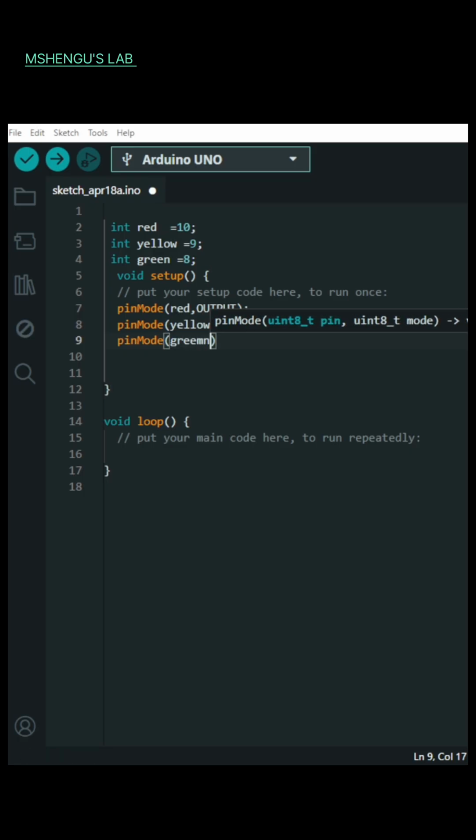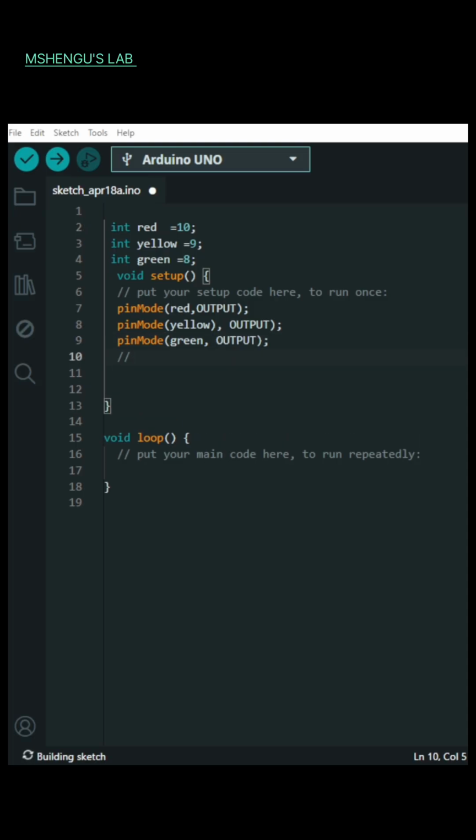That is where the processor will understand I'm setting these pins as output, so it's not reading analog data or any data at all. It just gives out an output of 3.3 volts of power, according to the specific timer that will be set.